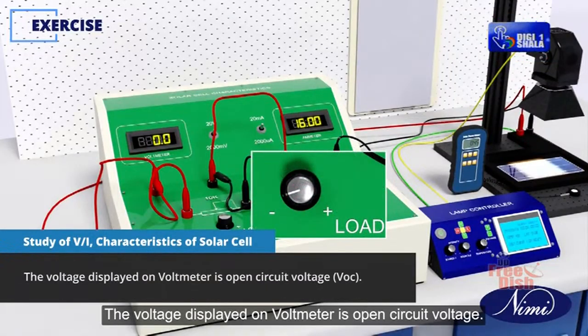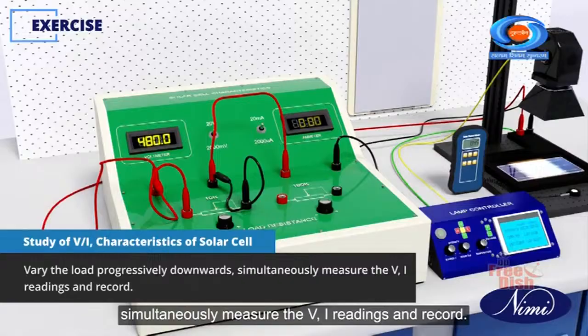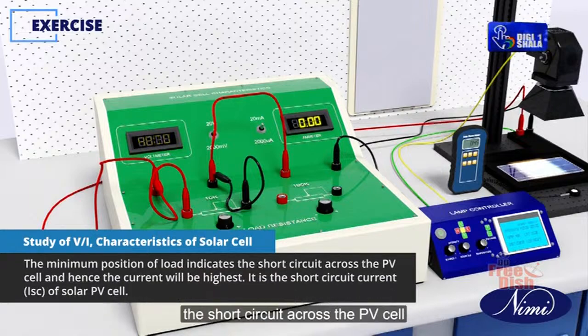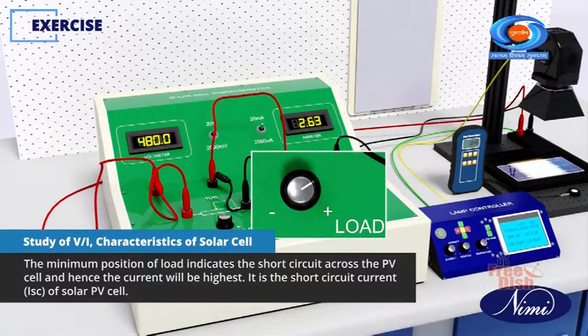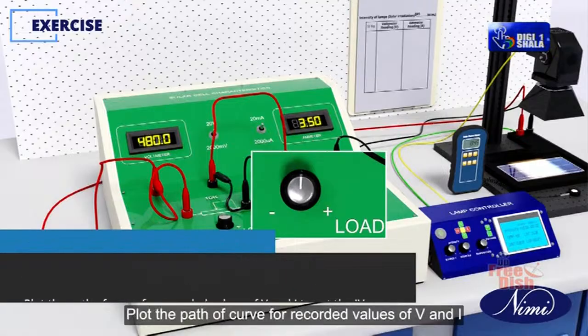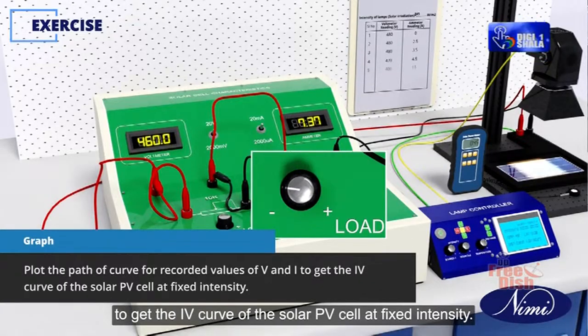The voltage displayed on the voltmeter is the open circuit voltage. Vary the load progressively downwards. Simultaneously measure the VI readings and record. The minimum position of load indicates the short circuit across the PV cell, and hence the current will be highest. It is the short circuit current of the solar PV cell. Plot the path of the curve for the recorded values of V and I to get the IV curve of the solar PV cell at fixed intensity.